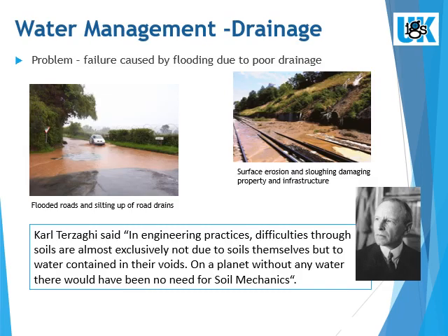Too much water in the wrong place is a problem in the world of ground engineering. If water isn't taken away fast enough, it accumulates or flows over soil, causing erosion. Then the silt blocks up the drains and the flooding gets worse. When water flows down a slope, it can cause instability in the surface or even lead to a deep-seated slip where a whole embankment comes down.